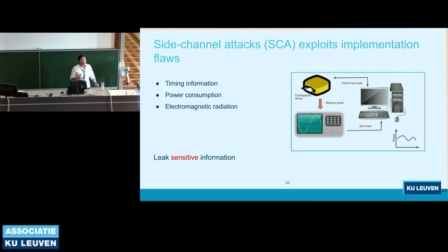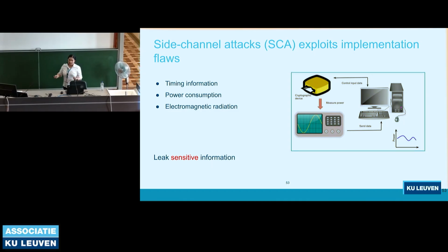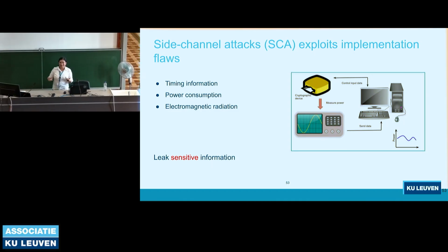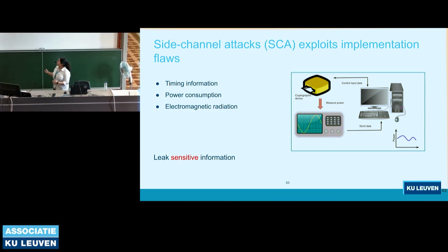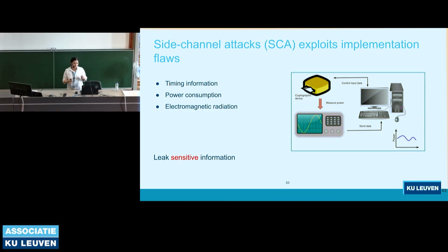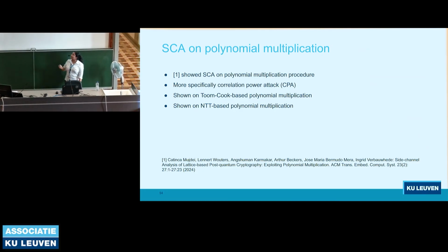Now, those algorithms are mathematically secure. These are implementation vulnerabilities, let's say. Implementation-wise, we tried our best in the reference implementation as well, right? We made it constant time. However, making it constant time is also expensive. Making it secure against power consumption attacks, something like SPA, differential power analysis or correlation power analysis, becomes harder and expensive. But if we do not do that, we have these attacks.